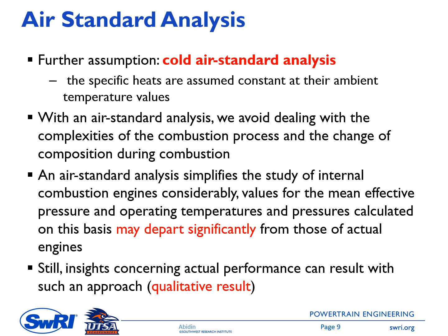And then an air standard analysis simplifies the study of internal combustion engines considerably. Values for the mean effective pressure and operating temperature and pressure calculated on this basis may depart significantly from those of actual engines, because we apply a lot of simplification here. Still, insights concerning actual performance can result with such an approach.